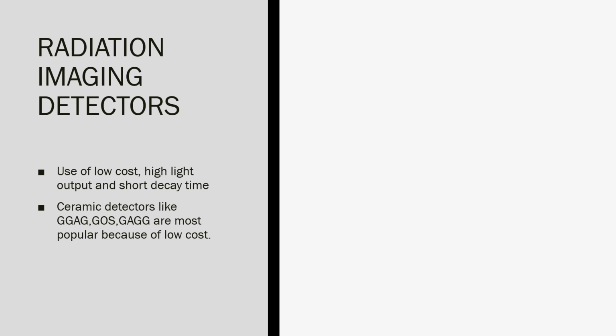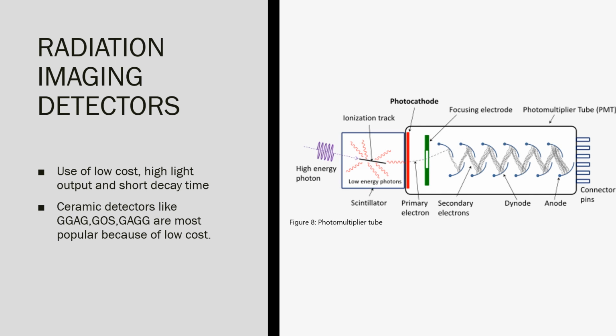Now let us discuss the operation. A thin ceramic detector is used as a scintillator coupled with a photomultiplier tube through a light guide. The photomultiplier tube detects scintillation light produced by interaction between the ceramic plate and radiation and converts photons to photoelectrons by the photocathode. These photoelectrons are multiplied by mesh dynode. These electrons are detected by the crosswire anode of the photomultiplier tube, and the anode signals are fed to the amplifier of data acquisition for position and energy calculation.